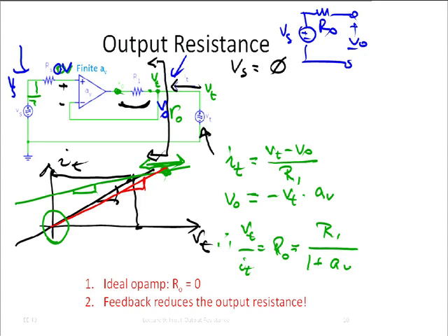In practice, this resistor, yes, ideally it would be 0. It's not 0, but then the gain, it's not infinite, but it's high. So in the end, we end up with output resistances that are less than an ohm and often less than a milliohm and so on. So it plain doesn't matter. Then you get a little bit of an error. I'm not sure whether I understood your question, but